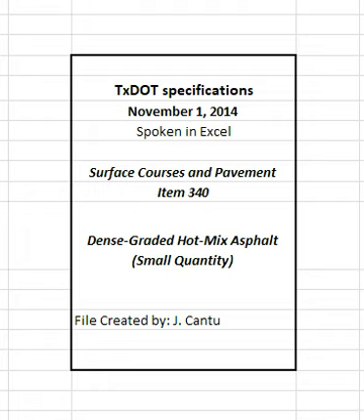4.8.3 Production testing. The engineer will test at the frequency listed in the department's guide schedule of sampling and testing and the specification. The engineer may suspend production if production tests do not meet specifications or are not within operational tolerances listed in Table 11. Take immediate corrective action if the engineer's laboratory molded density on any sample is less than 95% or greater than 98%, to bring the mixture within these tolerances.